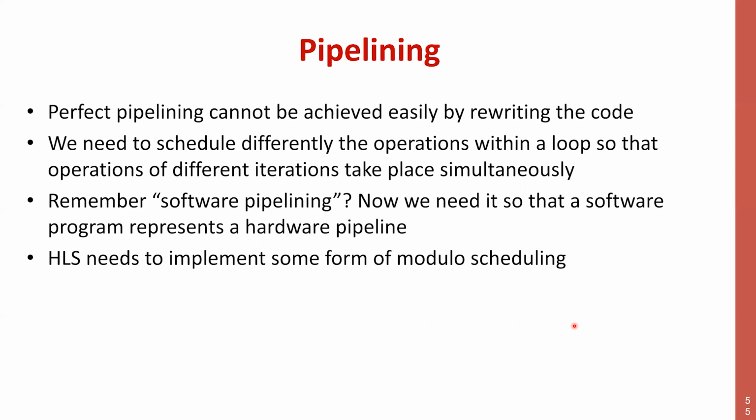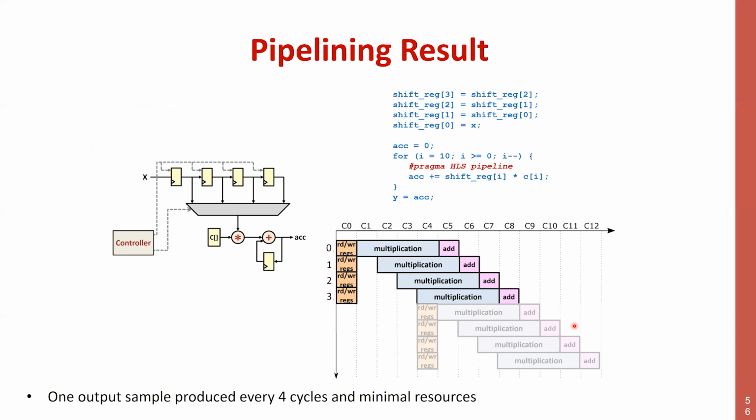And so I think you start thinking of VLIWs again and what we discussed there, and the software pipelining and so on, because that's exactly what you can achieve from this kind of HLS tools, is to restructure the computation by putting a pragma. Once more, you cannot do it automatically.